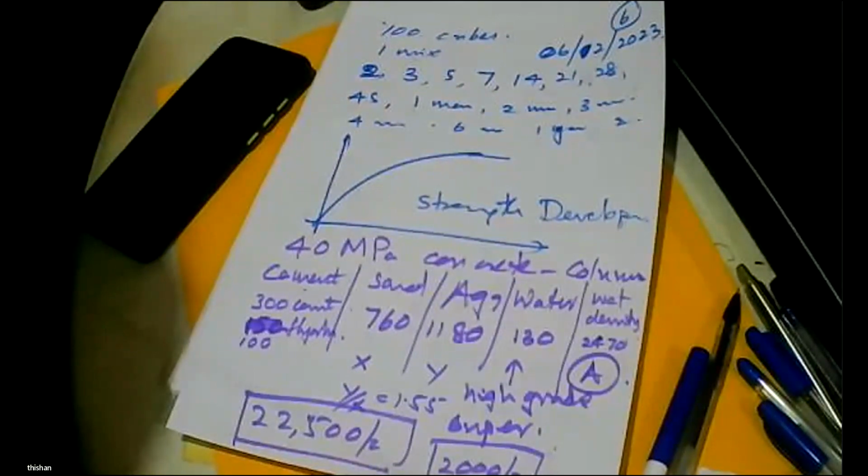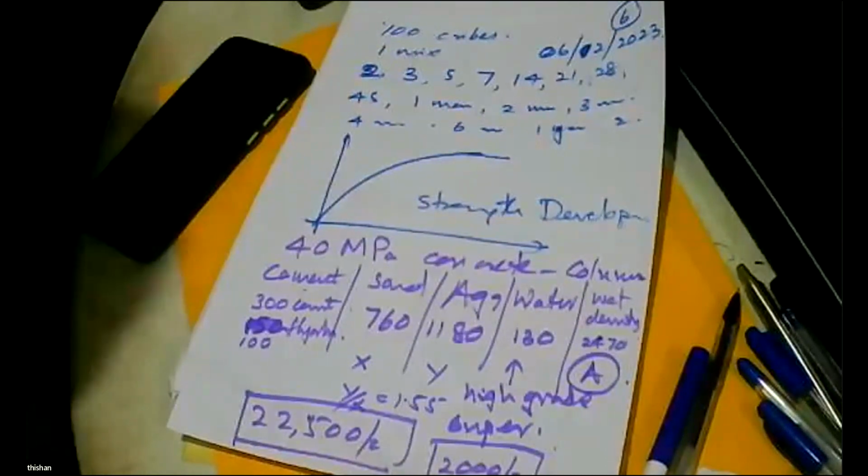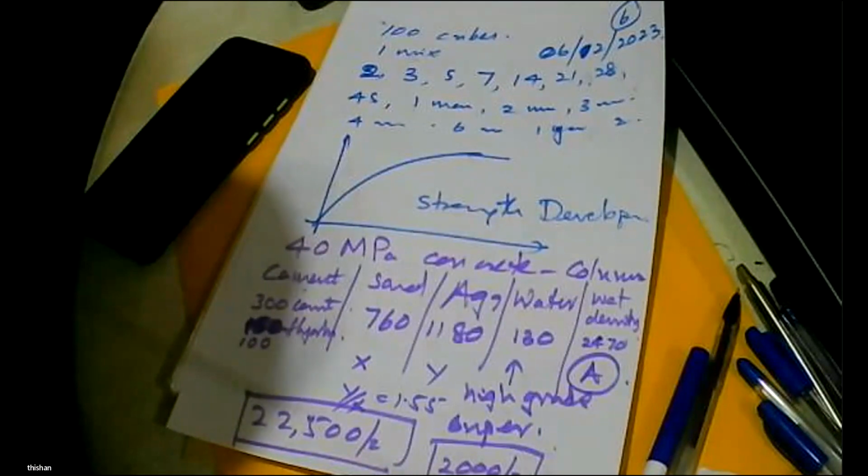Any other question, Mashika? Yes, sir. Then Engineer Ekanayake asked, how about the steel structure with this hollow pole? What is that? That hollow pole? That is pre-stressed concrete. It's not reinforced concrete. So that's why they wanted 65 megapascal in 24 hours to debond it. Okay. So it's a pre-stressed concrete pole. So it's a hugely stressed pole. So it's very strong. You would have seen this used by Sri Lanka Telecom.